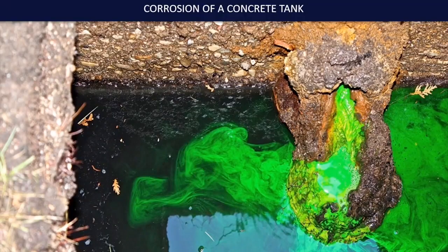You also want to look in your tanks to see if there's corrosion. As I described earlier, that's a cast iron discharge inlet baffle, but you can see the rust here. So over time, that will just slowly disintegrate. And eventually you'll end up with a potential safety risk there too, because the top of the tank could collapse. But it also has the potential to have water leak out around the pipes. So we have untreated septage or sewage leaking into the environment.